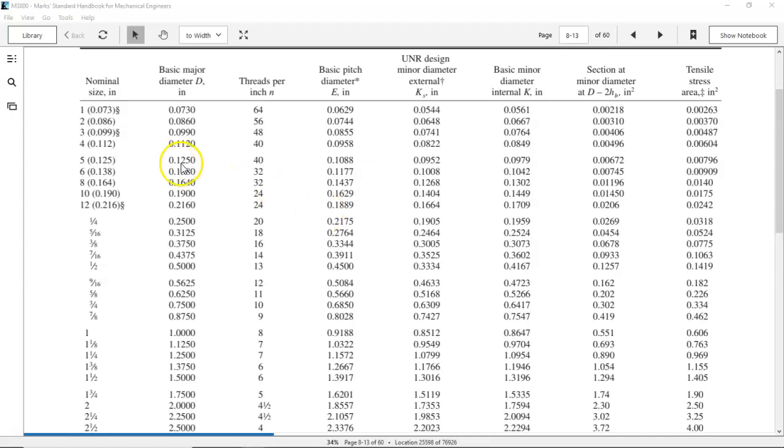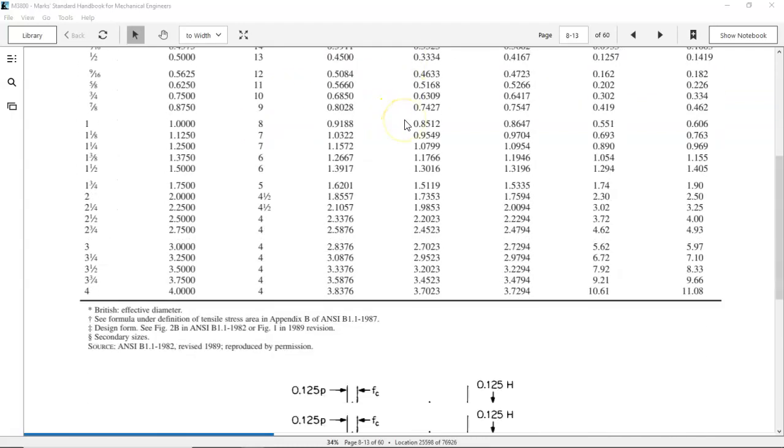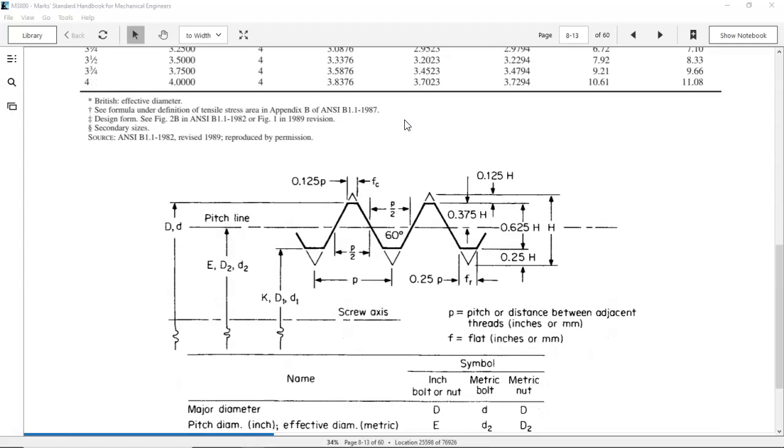So when we look at the major diameters, we can refer to the chart, number of threads per inch. Pitch diameters, really a lot of geometry that goes into creating this thread. So when we detail, we're probably going to see these as sharp V's. So we're going to include the triangles, not worry about the roots and the crest.